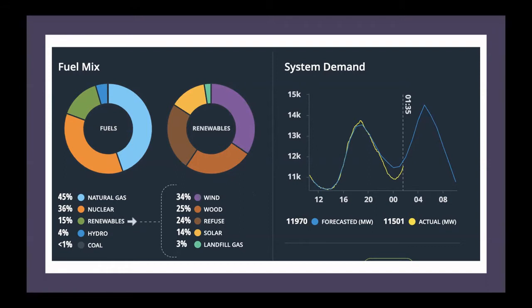If you see a typical load curve, it can be visualized as a load following sinusoid clamped with non-varying step load. In this diagram, you can see the variation is huge, that is of the order of 5000 megawatt, which is clamped over a step function of 10,000 megawatt.